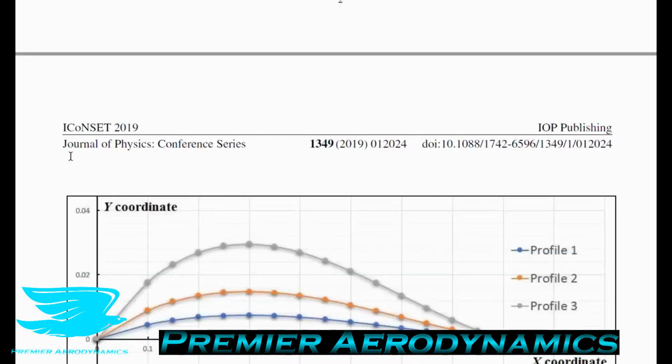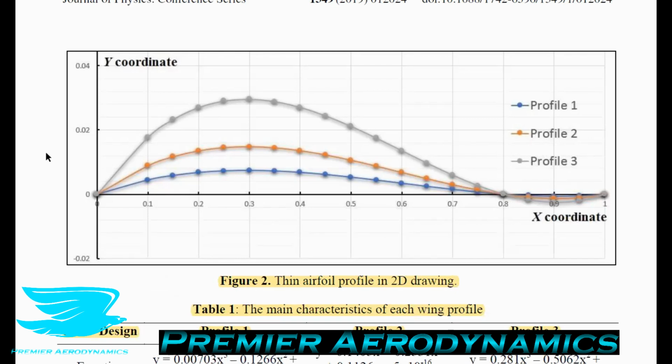This is because the Zimmerman wing planform already has been shown to be compatible with MAV applications. The main thing is that they fly at low Reynolds numbers, but you need to have fairly high lift coefficients. And Zimmerman airfoils have shown this, and we'll see it again in this paper here.